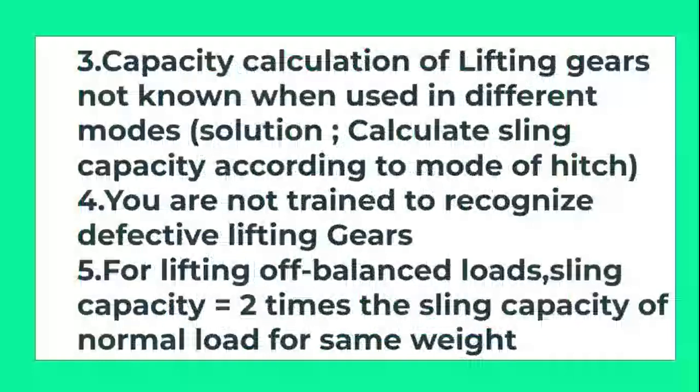You are not trained to recognize defective lifting gears. If you don't know how to use the lifting gears or chain block, or you don't know if it is okay or not okay, don't attempt any lifting operations.